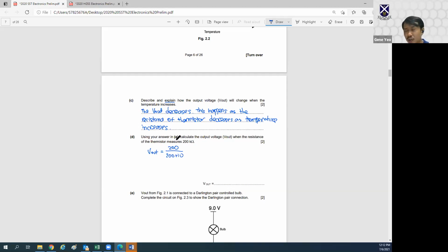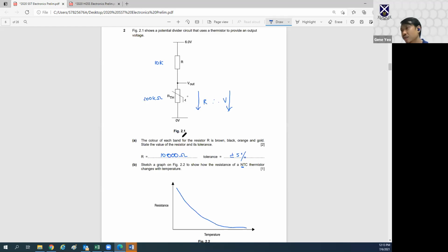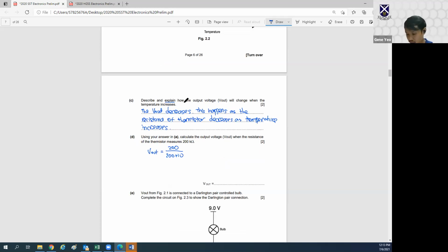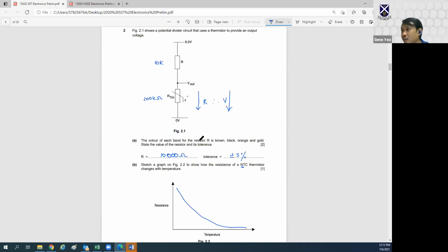Okay, so just to run through again, for some of you who are a bit confused about the voltage divider method, if I want to find the Vout in between, I always take this resistor, because this is the resistor that will use up the voltage left, this resistor over the total, to find Vout, right?